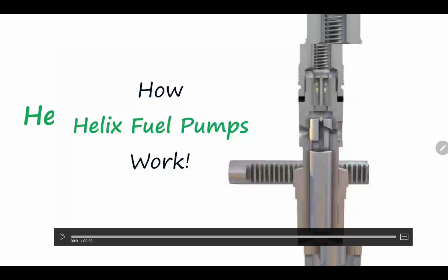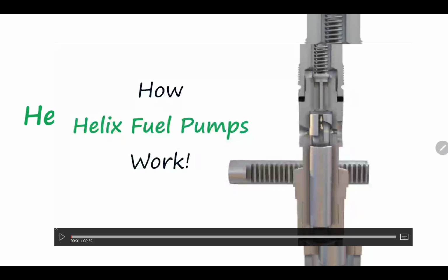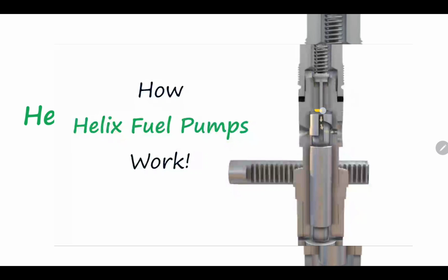So for the remainder of the upward stroke, it pushes the fuel from the top of the plunger back to the casing of the pump. So did the plunger inject all the fuel drawn before it started to move? No, it only injected part of the fuel. So how do we control the amount of injected fuel?